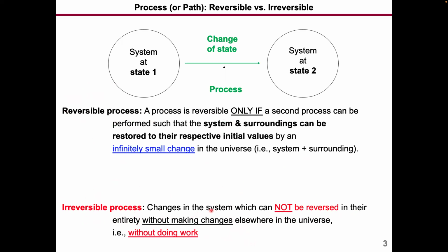But I want to quickly highlight that reversible processes usually have the following two characteristics. One is that the system is at an equilibrium state at all times. So remember, if the system pressure and the external pressure are equal, they are at the equilibrium state, meaning that during this change process, you control the external pressure or system pressure, maintaining them equal at all times. So you actually need to change very slowly. Okay, so usually it's a very slow process if you want to make sure the process is reversible.